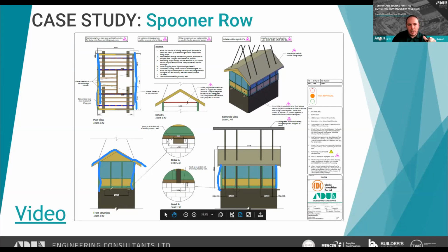So by understanding that, I also meant to mention the floors also span left to right, so they're coming into these walls here and sit into this wall here and this wall here. So we needed to come up with a way to make sure we picked up the loads where we could. The floor joists were very robust, shall we say, and the detailing of them was such that by supporting under those, we guaranteed we were picking up the rest of the structure.